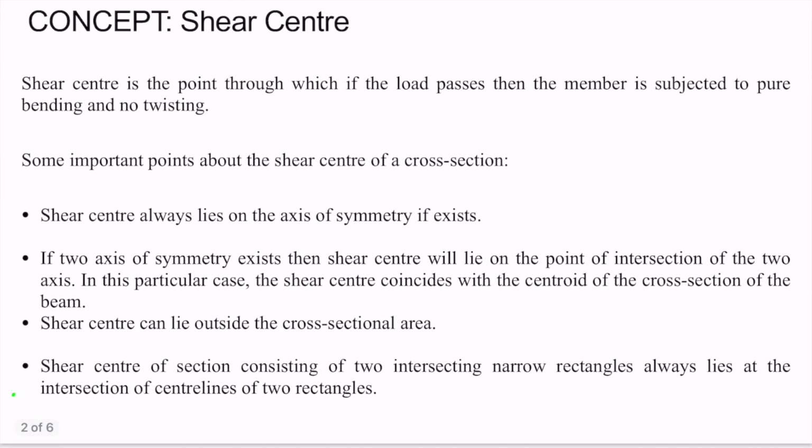So before moving towards the solution of this problem, let's discuss the shear center and a few points regarding the shear center of a cross section. Shear center is the point through which, if the load passes, then the member is subjected to pure bending and no twisting. So this is very important: the member will be subjected to pure bending and no twisting if the load is applied at the shear center of the cross section.